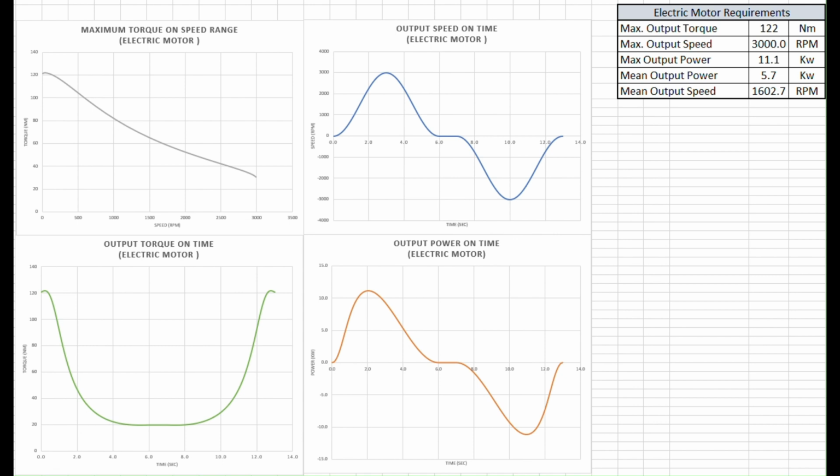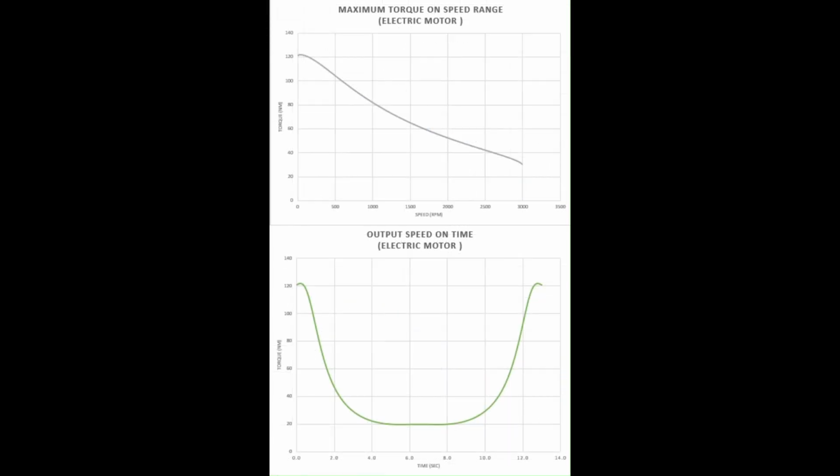The best motor selection for this application is a servo motor. Servo motors can deliver and maintain high torque at 0 speed. This is called static torque. A good variable speed drive and servo motor selection can allow a servo motor overload for some seconds. Let's suppose that we can allow an overload for a short time, let's say, 1 second. The nominal static torque required will be equal or higher than 100 newton-meters.